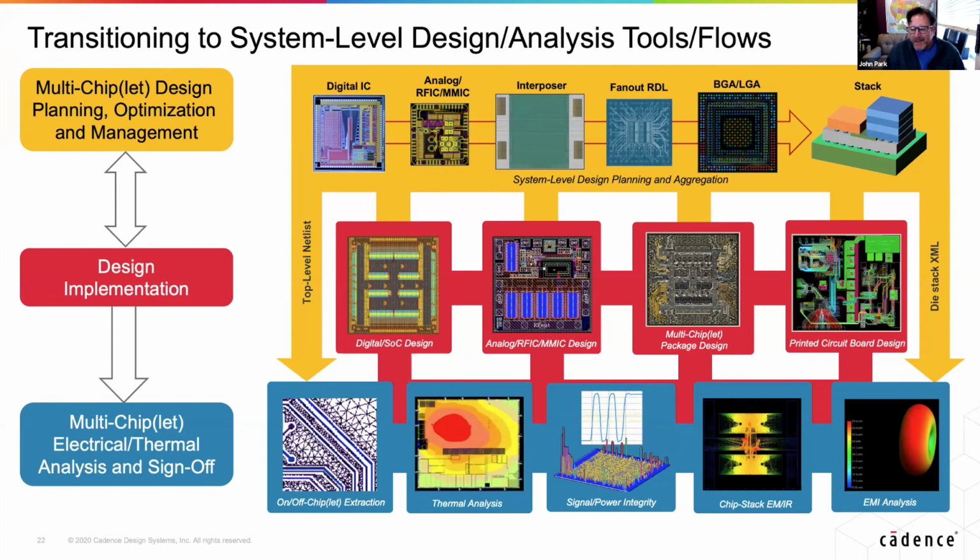The packaging, traditional BGA, LGA that these interposers and 3D stacks sit on, the board, that all comes into play, and then having that tightly coupled, as I said, with all of the EM extraction, signal integrity modeling, power delivery modeling, both on chip, off chip, thermal, both self-heating and mechanical parts of thermal, using computational fluid dynamics to look at airflow and those types of things.